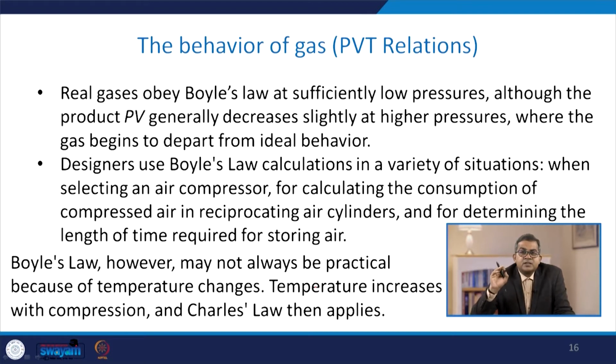Designers use the Boyle's law calculation in a variety of situations: when selecting an air compressor, for calculating the consumption of compressed air in reciprocating air cylinders, and for determining the length of time required for storing gas. Boyle's law, however, may not always be practical because of the temperature changes when you apply the pressure or the volumetric approach; then definitely the pressure changes will take place.